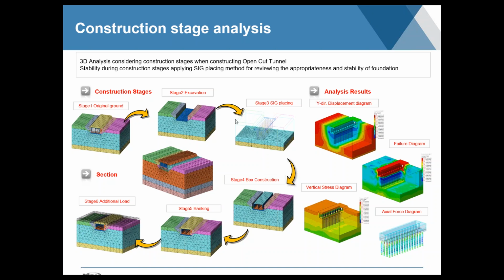Even for some kinds of analysis, the duration of each stage, if you need to consider settlement on softer ground, or dewatering, draining, preparing the ground for the project, all that can be incorporated into the stage analysis. And that's why it really gives you the most accurate approximation of what's going to happen in your project.